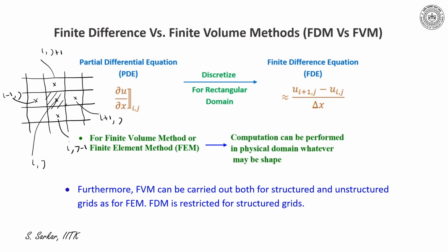Thus, for this rectangular mesh, for a given differential equation, I'll first discretize the equation and create the finite difference form, and then with some numerical methods I would solve this finite difference equation, and thereby I would evaluate the variable at every point which is denoted by the node for a given mesh.